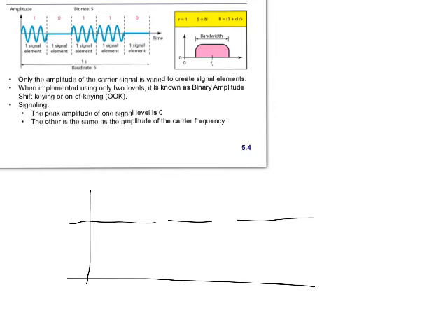Right? So with any change in the amplitude, like if I have a sine wave like this, and then I have 0, sometimes this cannot be detected as an actual sine wave. If the amplitude is very small, then I'm going to interpret it as 0. And this happens no matter what you try to do. That's why we say, for example, for UTP, the length is 100 meters. Why? Because after 100, the signal becomes very small.